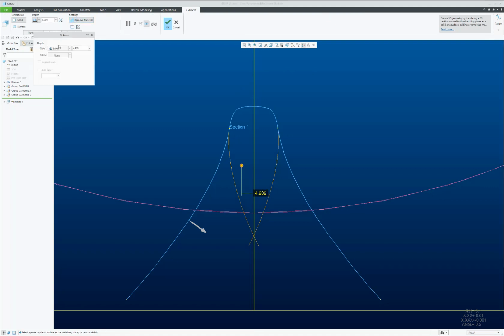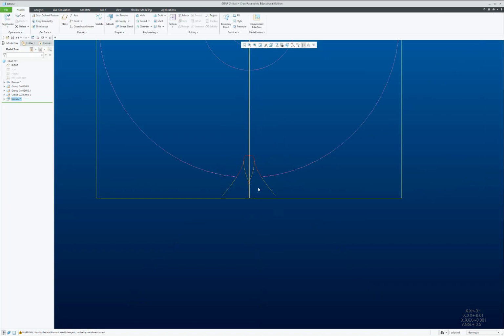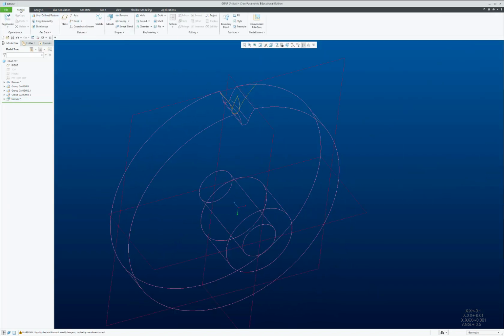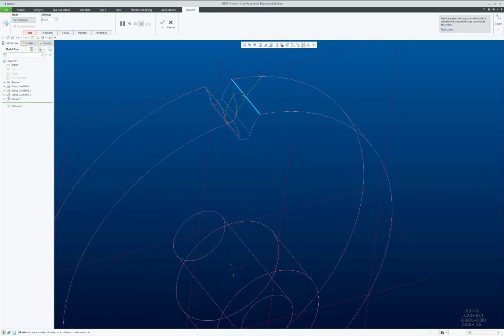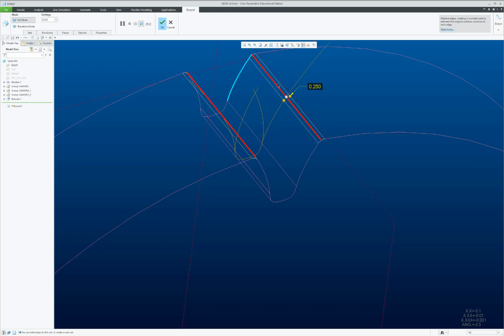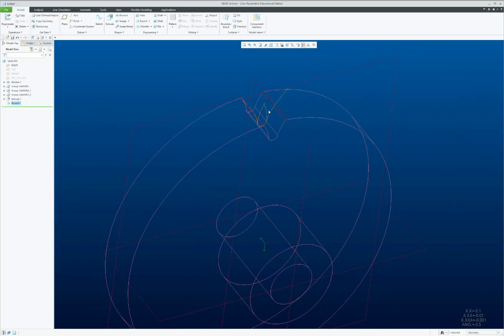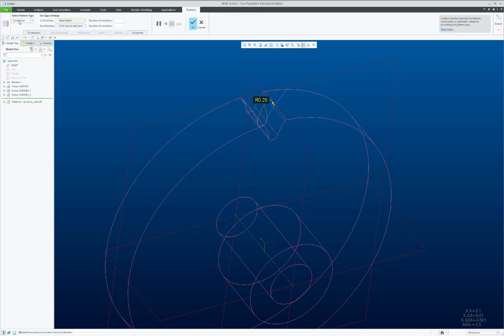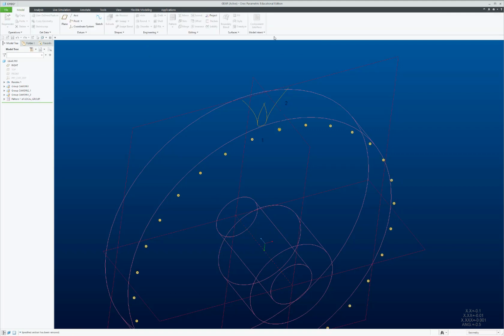We will remove material all the way through on both sides. And that is one tooth. Create a round that goes here and goes here. The size is 0.25. It will be equal to AD coefficient. Group the 2 components. And let's show the axis. Pattern the group with an axis option about the central axis, creating 30 of these teeth equally distributed.